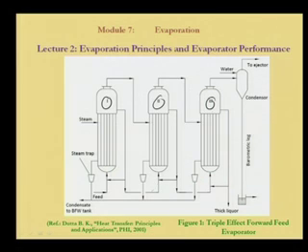So the boiling point is increased, and we have to reduce the pressure in any case to get into the boiling situation, to get it boiled. The reduction in pressure in this effect will not only make this thick liquor boil at a lower temperature, but also allow the vapor to come to this, and similarly this happens. So there is a gradual decrease in the pressure. The feed is in the forward direction, getting more and more concentrated, and the vapor is also going in the forward direction. This is what is called the forward feed.